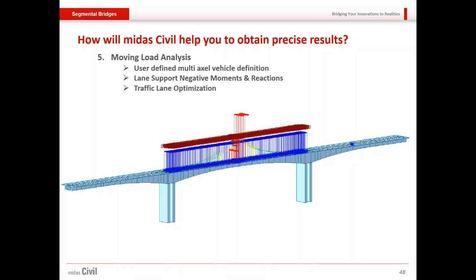and that bending moment would be shown. Similarly, say if you are not actually doing a box girder bridge, you are doing a I girder bridge, PSC I girder bridge or something, then in that case, the traffic lane, which is defined only in a single line, the vehicle has certain width of say 2 meters and your traffic lane might be say 3.5 meters.